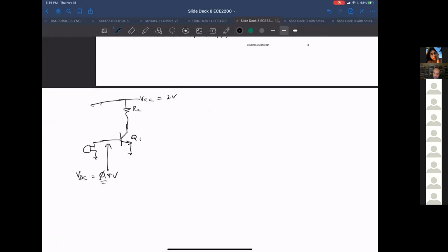And I want to have my input signal from the microphone. So let's say that's 20 millivolts. I'd like that to ride on this 0.8 because that puts me in the right place for this amplifier to gain up this 20 millivolts properly for me. So I'm looking for a way to do that without putting a battery here.